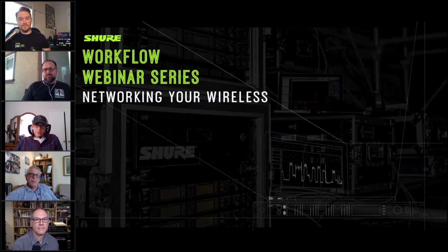So now how do you react to failures? Doing it the old analog way, mixers wouldn't even know a failure happened. Now, all of a sudden, you're communicating to mixers that instead of opening RF1, they have to go to RF64, the backup to the backup's backup, and getting them all to react and open that mic up in time doesn't seem to work real well a lot of the time. So wrapping our heads around how to deal with the Dante side when a failure happens is something we aren't real comfortable with yet.